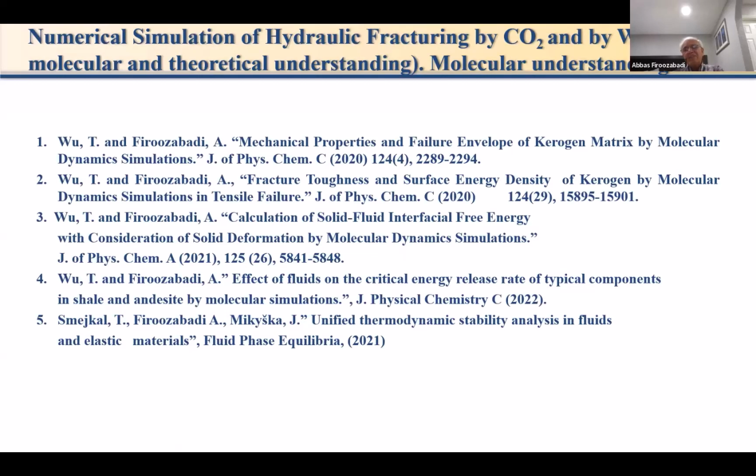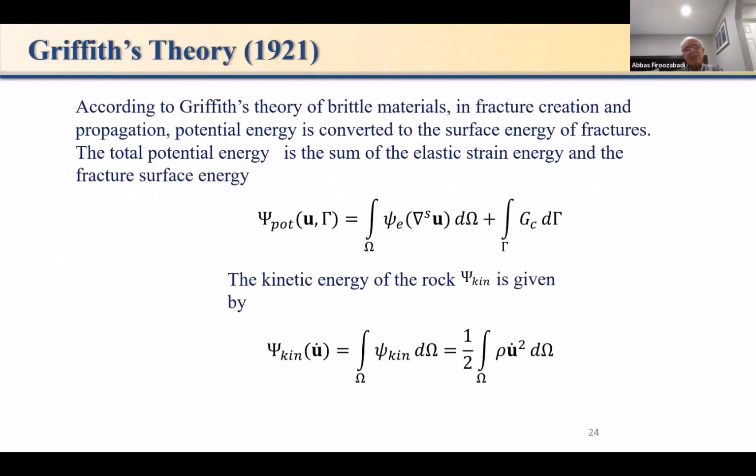In our case, I started with a lot of molecular simulations to get knowledge of the process. I've listed some of the work we did to understand fracturing. Now, part of the idea of the phase field is Griffith's theory, that potential energy is not only related to the work from the stress or strain part, but also related to surface energy. This is over the volume, and this is over the surface or the line, depending on 2D or 3D.